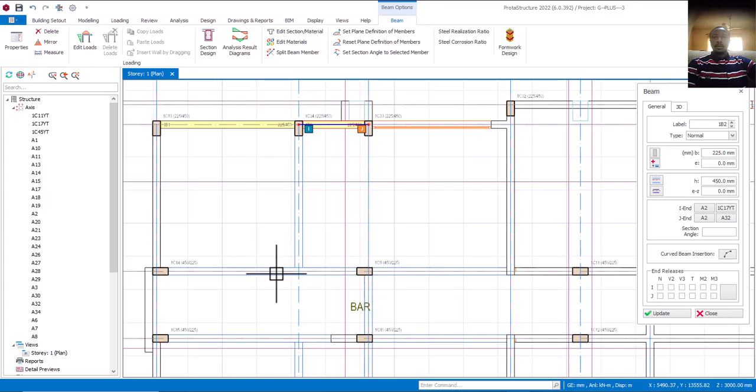So we also come here now, take the property of this from this point here to this point. You can see it's very straight. Is that okay? Click on it, right click and also stretch from here. Let's take it out. Right click again, offset, sorry, click on it, right click, stretch from this edge to this edge. That is fine. So now it's time for us to have our wall. I can click on wall. What wall are we having here? So the width is what? The width is 450.